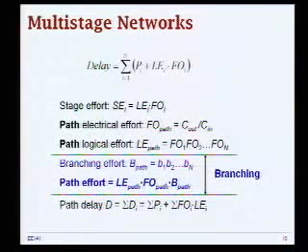I can define my branching factor. I can easily and nicely calculate delay. Then in that case, this theory is bulletproof. But if you have to do some sizing optimization and then you have gates that branch off, then you have to be really careful. Then you have to see if really this concept of branching does apply.